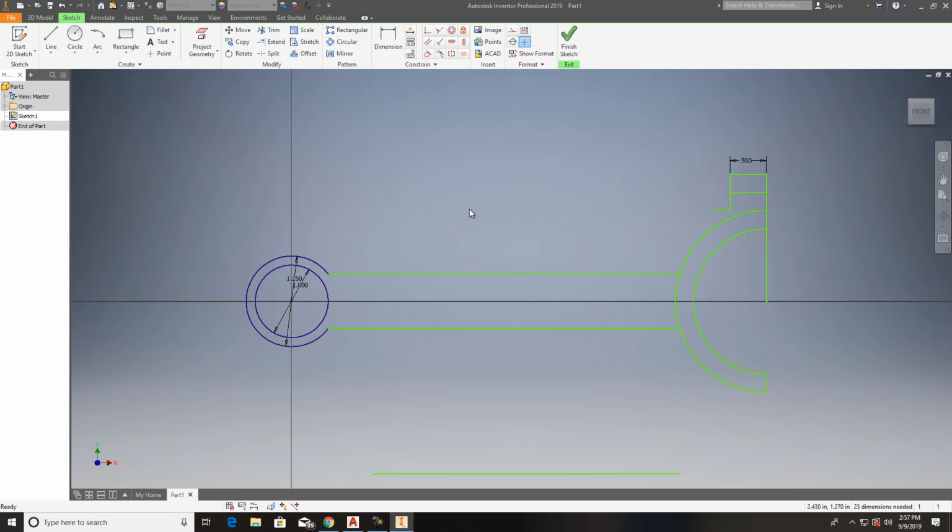Now I want to show you an old school method here that's worked for years. This is a drafting technique, but I want to show you 2 different techniques. Let's show you this old-fashioned technique here. And what you want to do is click on this circle and click this end point because you want that tangent of that arc to hit this point. Click there, and the radius is 2, so your diameter would be 4.